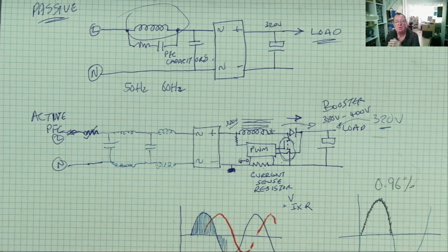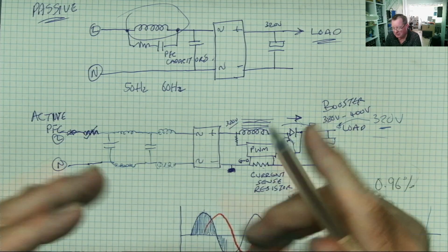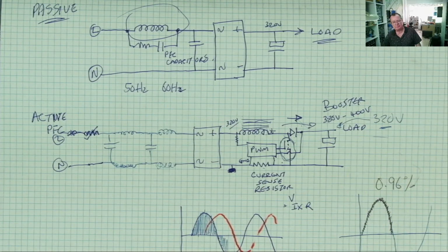So that's where you can diagnose those sort of issues when you have one large PCB containing a lot of different parts of the device and you're not sure exactly where the problem is. So you can often disable the PFC, and that's quite a good repair technique, okay?